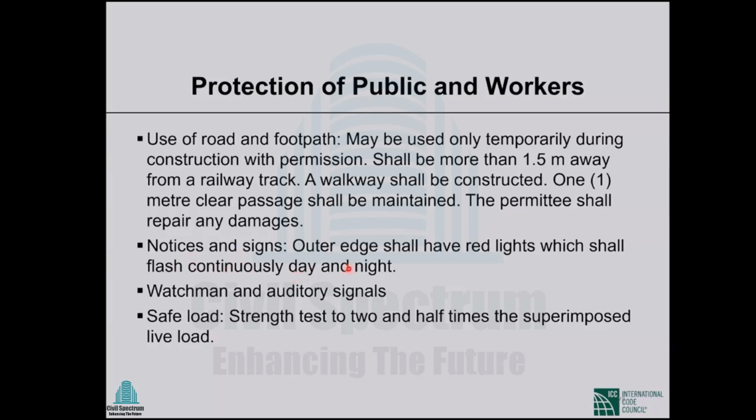If we use some place which is near to public use, then we should have flashing red lights. You might have seen some of them with the metro rail construction or elevated expressway construction. There you can see places where red lights flash. That is actually a code requirement. In places where you need to control the public, you need to have watchmen with auditory signals, that is whistles.